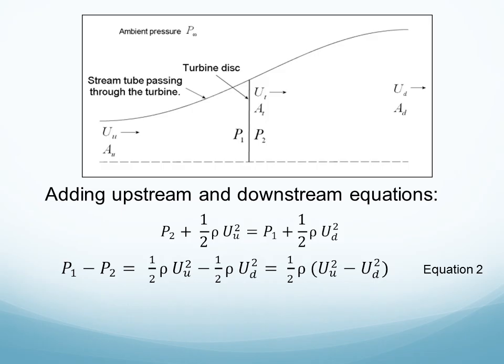So at this point, I want to touch on a slightly different approach from what we've done so far, and it helps to explain the shape of the flow depicted in our diagram, or in other words, why air expands through a turbine. So we know that turbines convert some of the kinetic energy of fluid flow into mechanical energy. If we write Bernoulli's equation from upstream to downstream, we remember from class that the energy due to a turbine is negative on the upstream side of the equation, or can alternatively be written as a positive value on the downstream side of the equation.